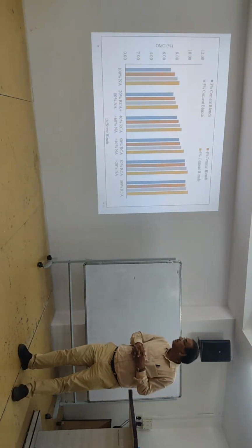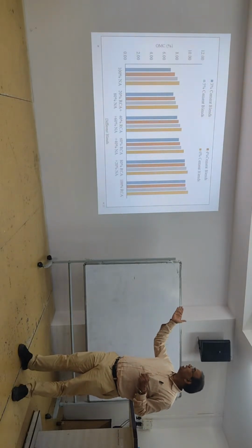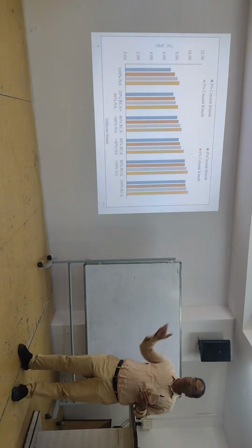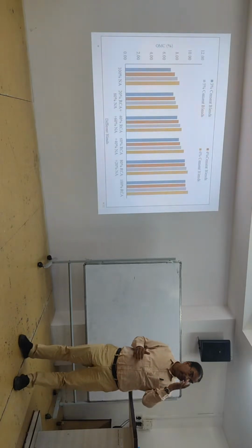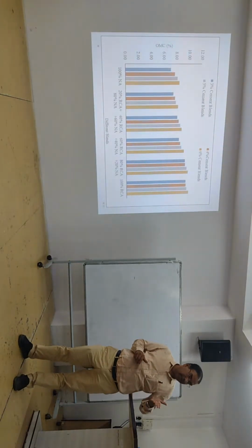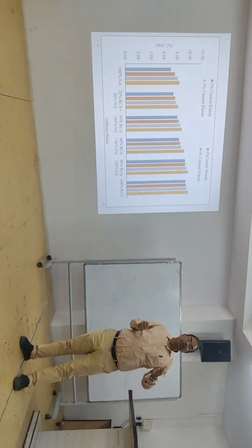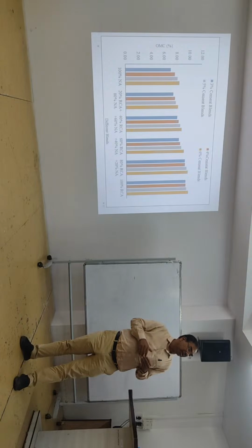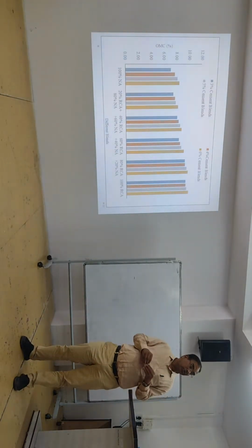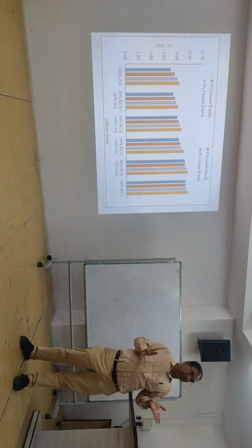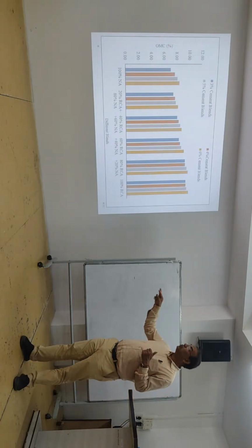OMC, the optimum moisture content, we can see 100%. We are having, we can certainly see, the maximum water content. So again, there are different technologies we should use. Some chemicals are available, like a company called Zydex in Gujarat, that gives a chemical that makes your water absorption become 0. They put the chemicals in such a way that the water absorption of the soil becomes 0, so we can make it impervious. But the problem is that the cost will increase.